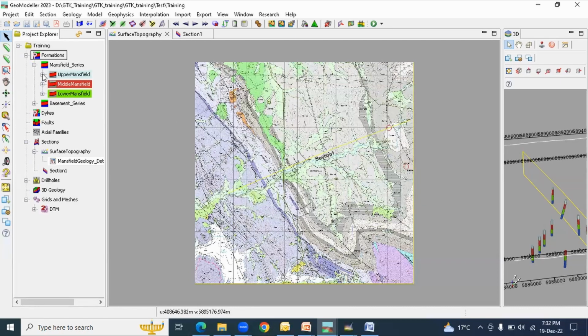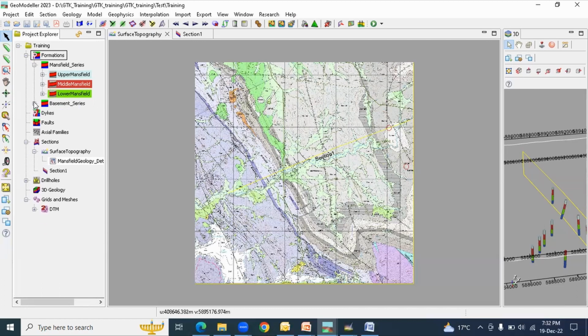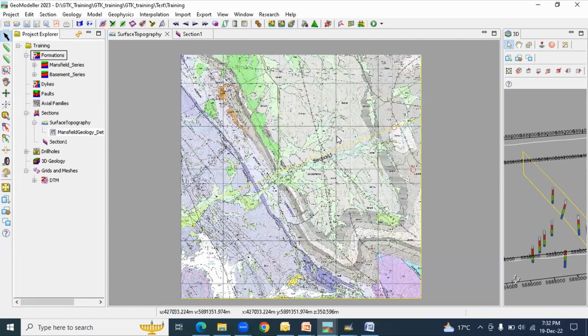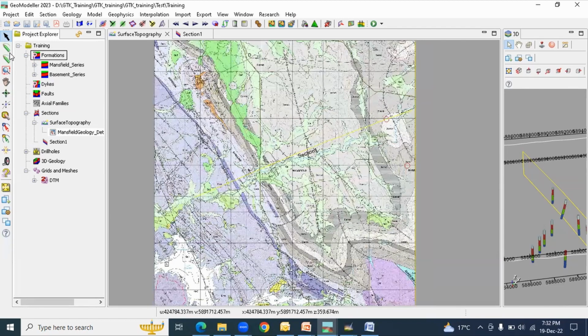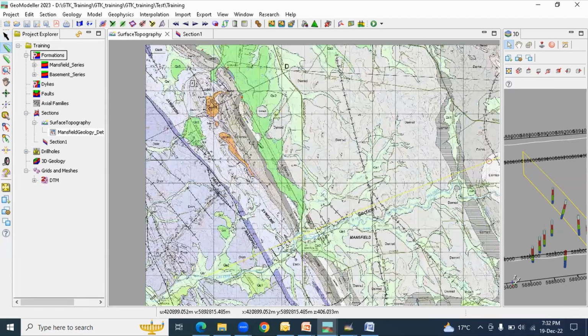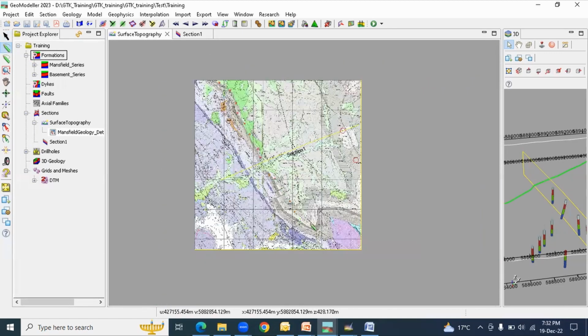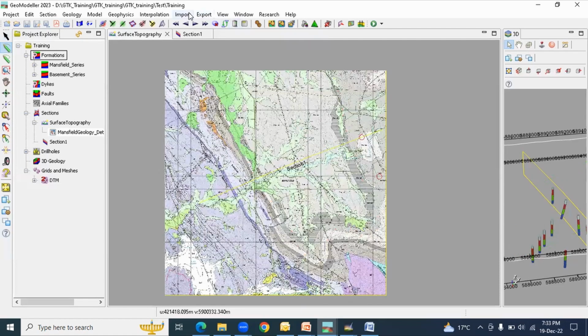Now we can see this information is here, and the basement information. Then the next thing is to import the geological layer. There are many ways we can do this. We can simply digitize the upper Mansfield bottom layer by taking a pencil, just a random sketch, or I already have the digitized coordinates saved as a CSV. I can import that into this section.